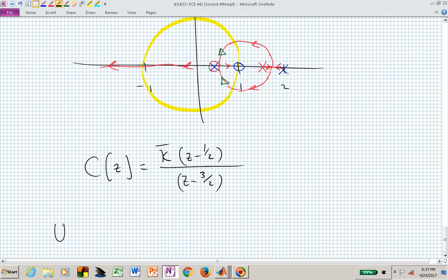But what we're seeing is that an unstable controller pole allowed us now to not have us fixed always between 1 and 2 with a branch of the root locus, and that unstable controller pole is now actually helpful in stabilizing the closed loop system.